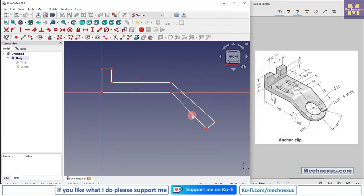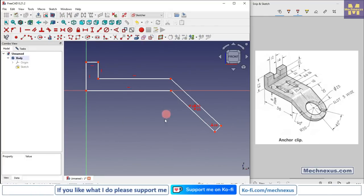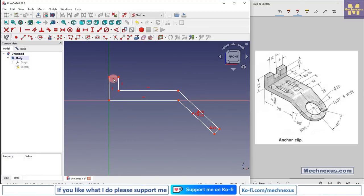And now here we will select this and this and add a parallel. We will select this line and this line and add a perpendicular, and let's give the dimensions. So first one is of thickness.